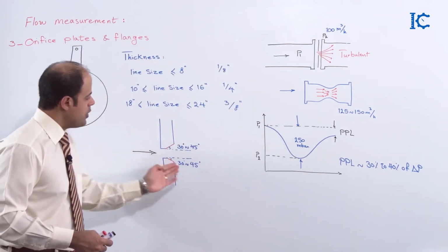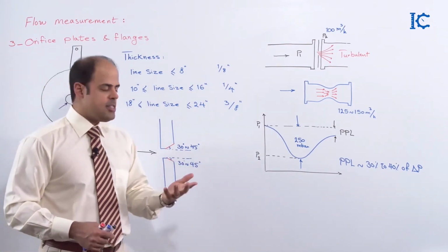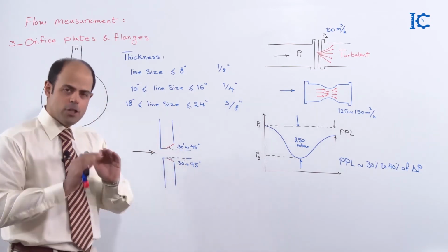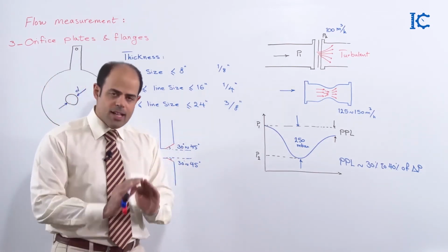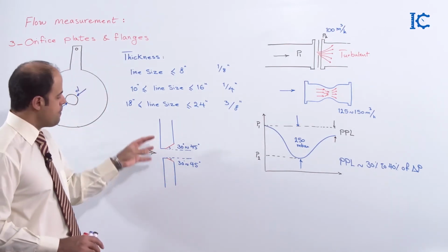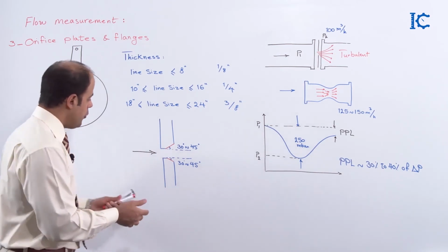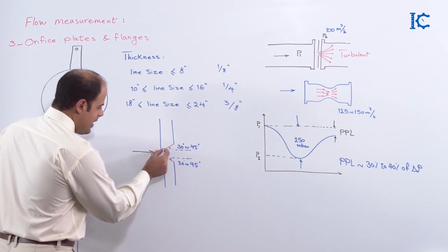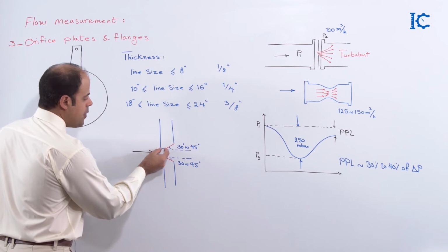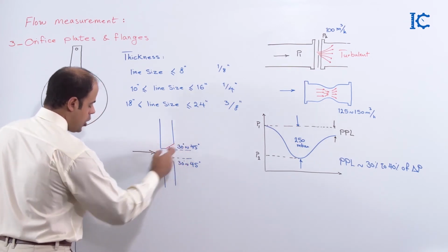And for sure, with the passage of time, after a short distance, the turbulence which has been formed between these two parts would be totally suppressed, settled and subsided. So by means of this shape, we can tackle the problems as well. But do not forget, as you can see, a small part of the orifice must remain unchanged, and after this part the conic shape starts.